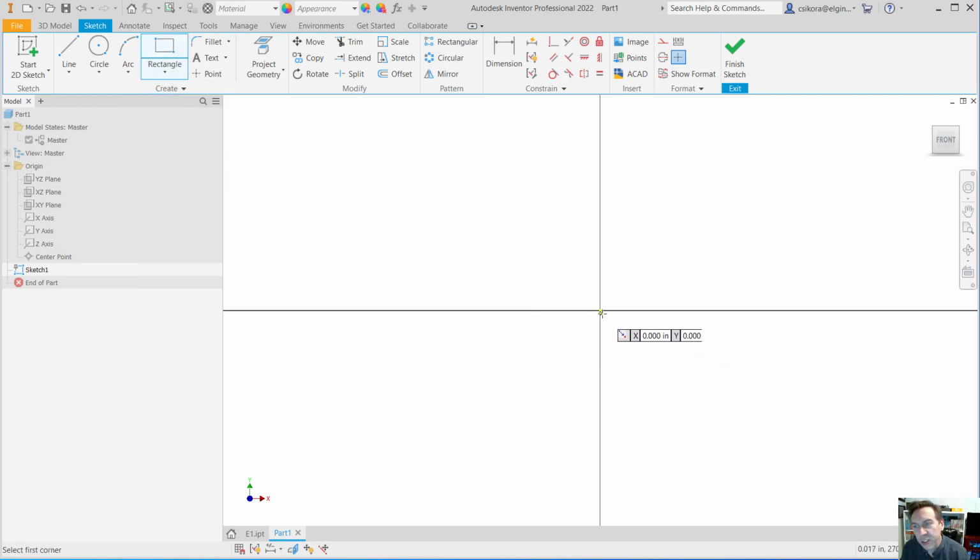Now right at that origin, see that at the center of the crosshairs, there's that little yellow dot. If you set your colors differently, it might be a different color, so don't worry, but just know where you're at. That's your 0 marker. Let's go ahead and click one time, move your pointer up and to the right, and you'll see you could input information here. So we want it to be 3 for the first one, so 3.00. You don't have to type in the zeros or the point, just type 3 and hit Tab on your keyboard to go to the next one.